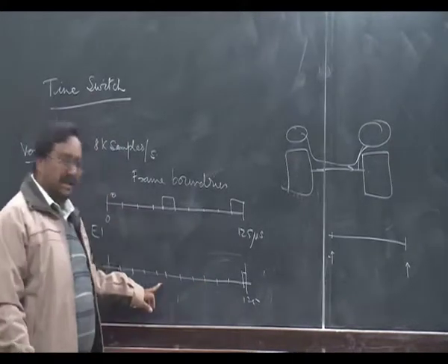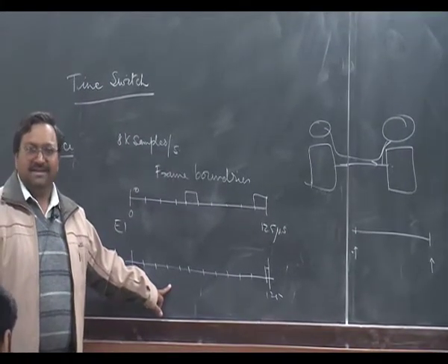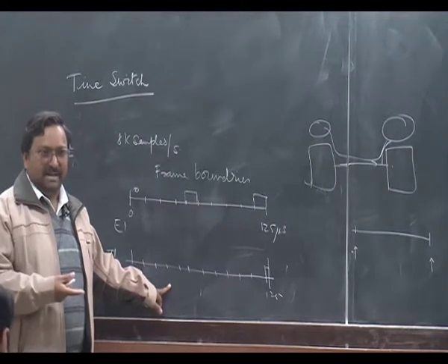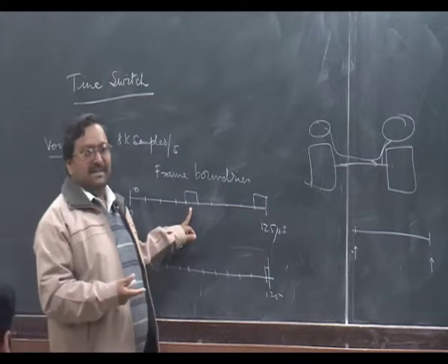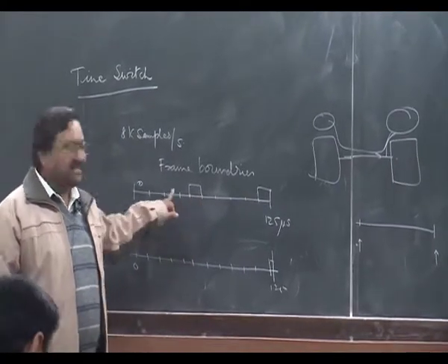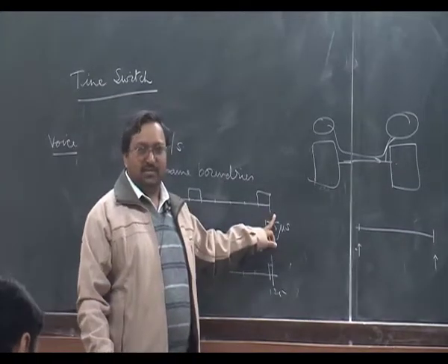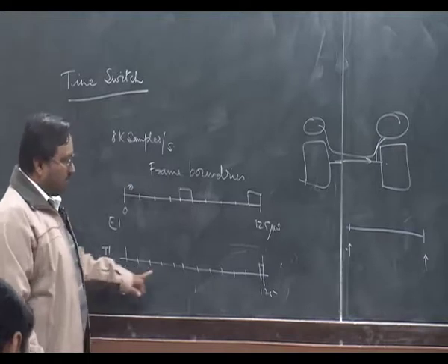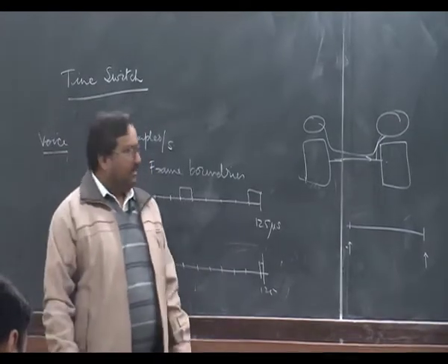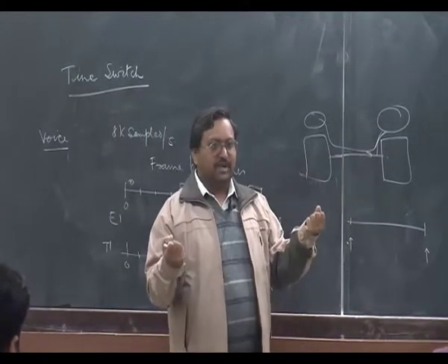That is either carried by one bit in every octet, every 6th frame in the T1 carrier system, or by this 15th slot. I always start the slot number from 0. So 0 to 31 is a 32 slot system, and 0 to 23, one extra bit will be added. All this is going to be stripped off before you can do switching.